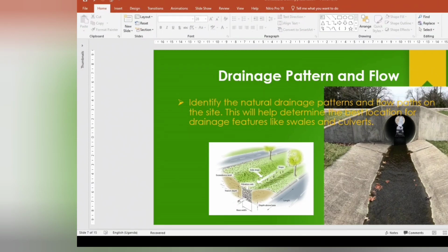Then we can also look at another illustration here. This is the cross section. This one was a 3D. So we have the permeable block paving, which is these ones, have the sub base, and then geotextile. That's what we have. Then infiltration, meaning the runoff water is able to infiltrate into the ground, which is going to limit issues of drainage in your compound.